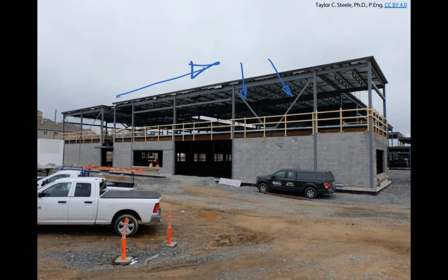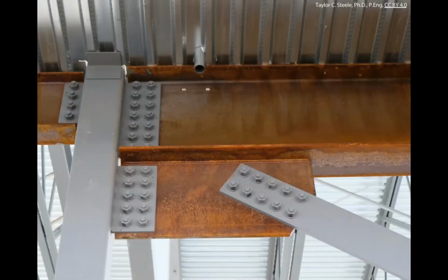That's not going to help us much. So basically all that load's going to get transferred into the tension brace, and that's going to come through into the brace that's buried in the wall here. These braces are more or less going to just give out of the way and buckle and not contribute significantly to the resistance of that building. And we're going to focus today and for a couple lectures on bracing that might look something like this, and how these kinds of braces are connected.